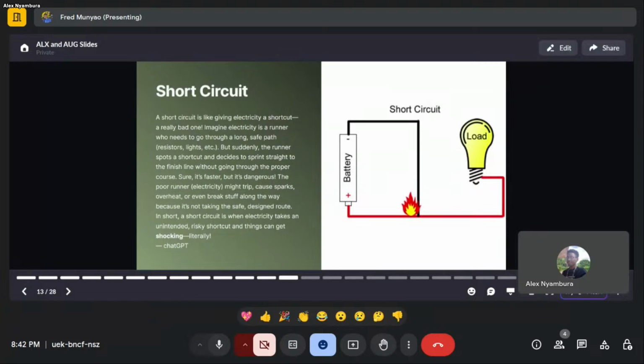If we connect the 5 volt bulb to 250 volts, that could also be called a short circuit, so we don't necessarily have to connect the positive directly to negative. The same applies with microcontrollers. If you connect the positive, which is the VCC, to ground, you can even destroy your board, which is the microcontroller. So you should avoid connecting the positive towards the negative, even if it's accidental.